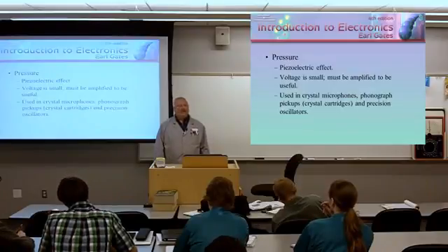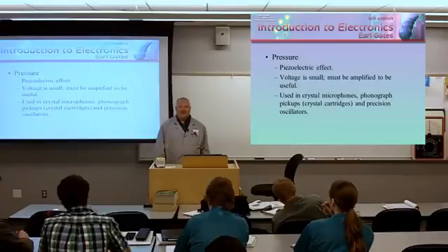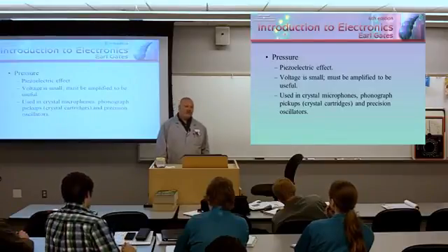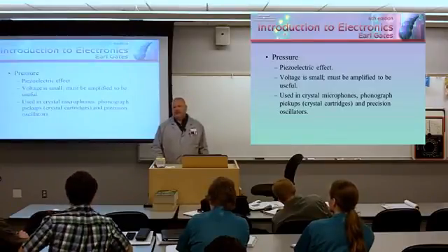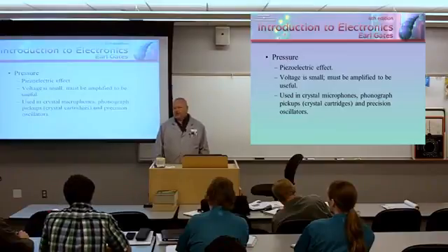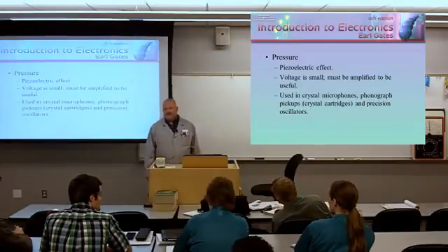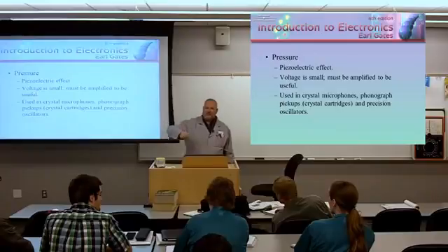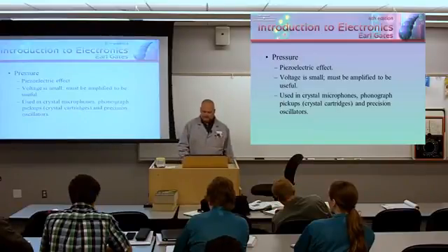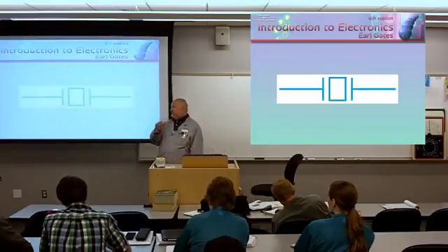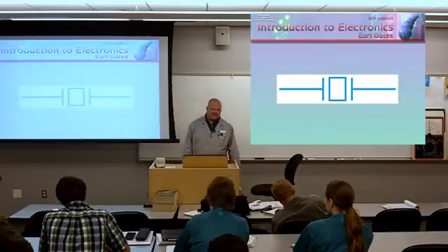Also, these are used in a lot of engine sensors now, right? You could monitor all types of different pressures, your oil pressure, your cooling system on board an aircraft, your hydraulic pressures, all of them. Little sensor. That voltage gets amplified, sent into a computer, and then you can look at all this virtual instrumentation. Simply doing it by applying pressure to a crystal. This is what the schematic symbol looks like for a piezoelectric crystal.